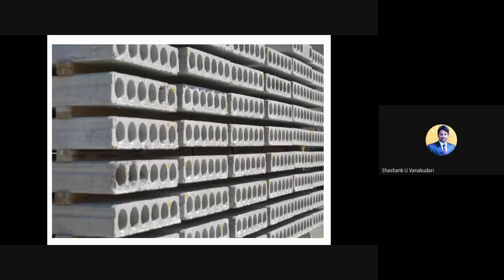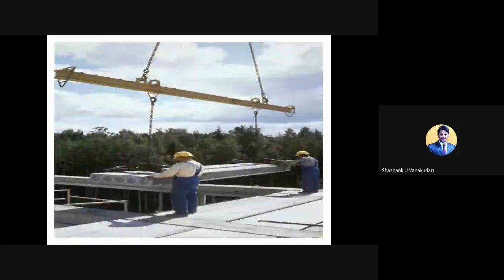Okay, and here you can see how these RC planks have been placed. This is the erection process. As I told, depending upon the length and the weight of the member, the erecting equipment is chosen, and then the supports while erecting, or these hook connections they have placed here, depend upon the total length. They fix these erection connections, and then standard supporting members are also provided here.